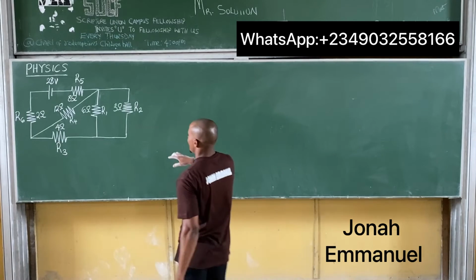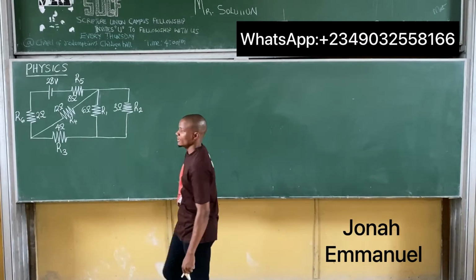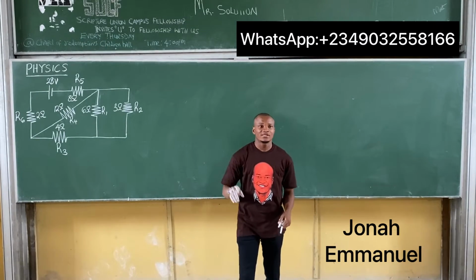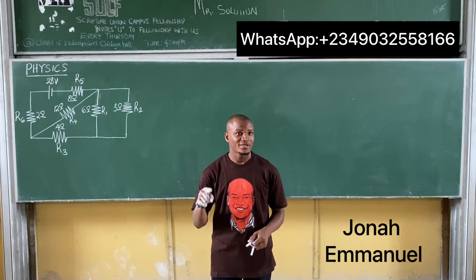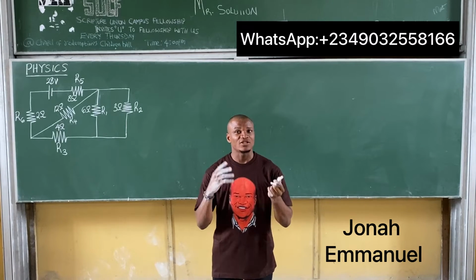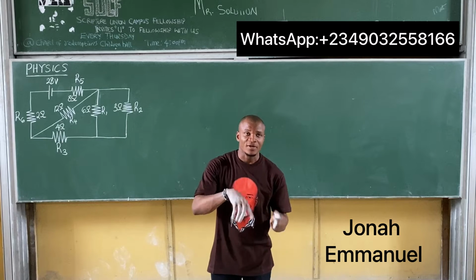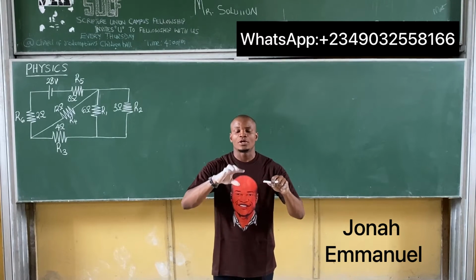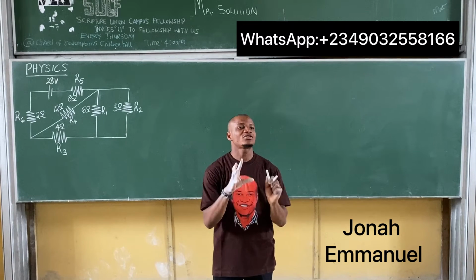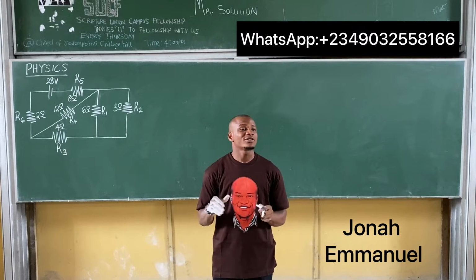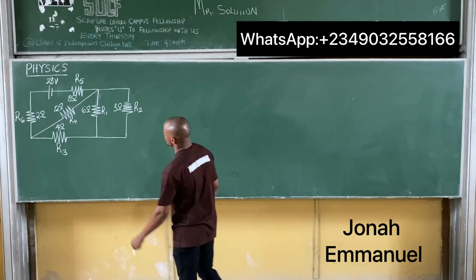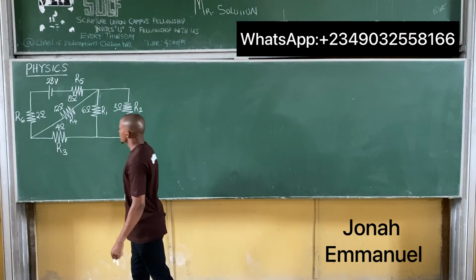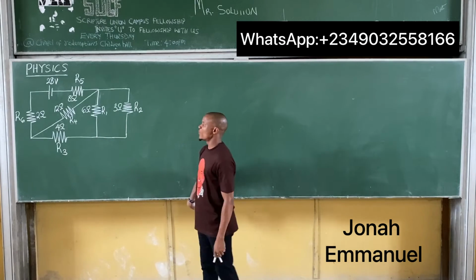Alright, so we have to find the equivalent resistance here. What we use here is called the circuit reduction technique. Take them either in twos or in threes. And I said when it comes to a circuit diagram, where do you start from? You start from the closed end to the open end. In this case, there is no readily closed end, there is no readily open end.